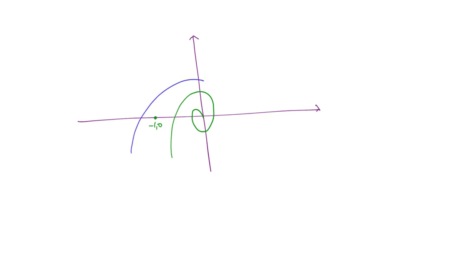So you can see an example here for various time delays. Let us say the point minus 1, 0 is here. Let us take one function like this, and another function, let us say it is going through like this. Let us say the time delay here is t d1 and this is t d2. You can see that this system is unstable because the intersection is towards the left, whereas this system is stable. Now what is the relation between the time delays td2 and td1? Which one is higher?